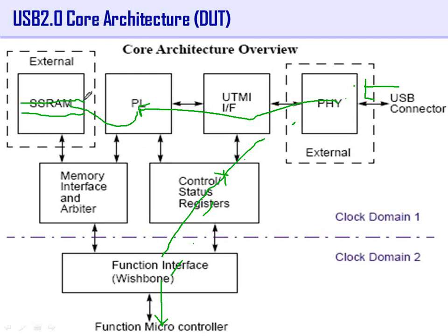Those locations are what we are calling buffer 0, buffer 1. Even buffer 0 has two things: what is the pointer, and what is the size? Accordingly, it knows where to stop putting the data, then where to wrap back. It is not infinite memory, right? It will start writing, and once it reaches the upper boundary, it comes again to the lower boundary.